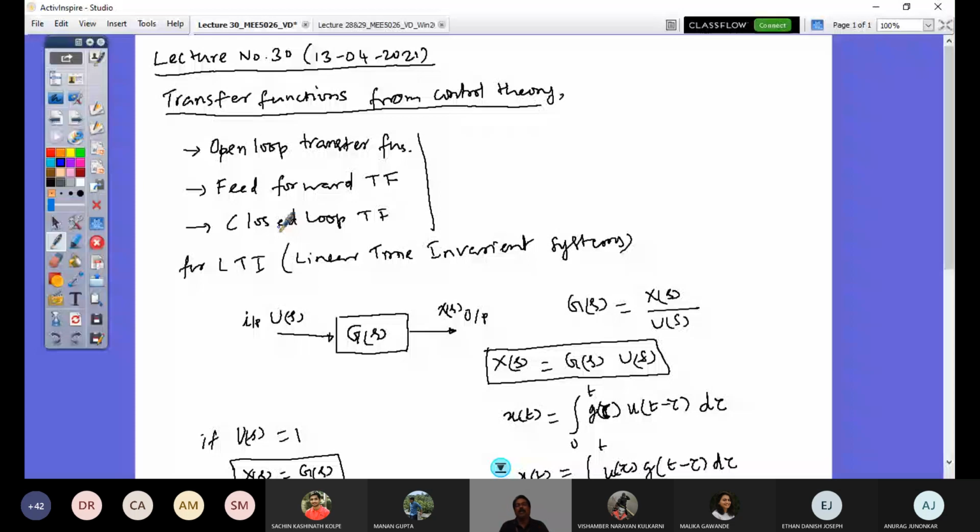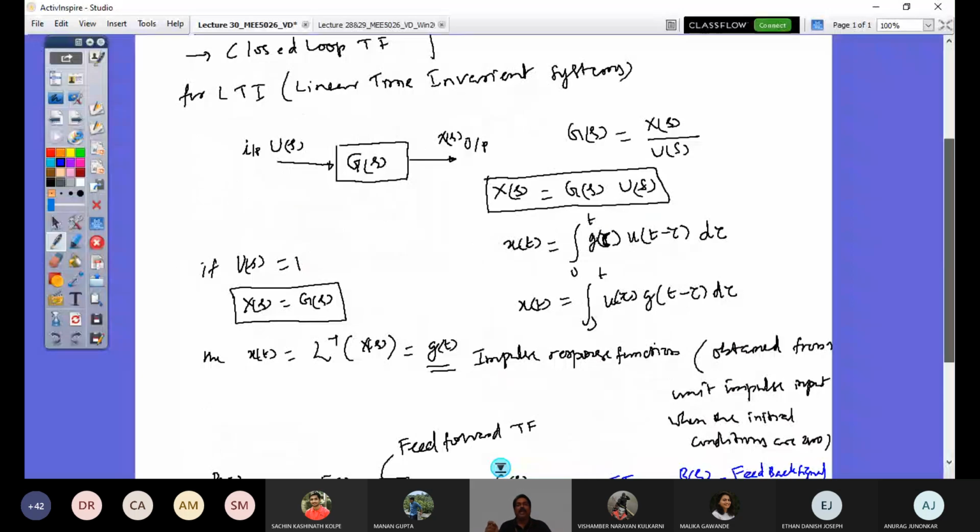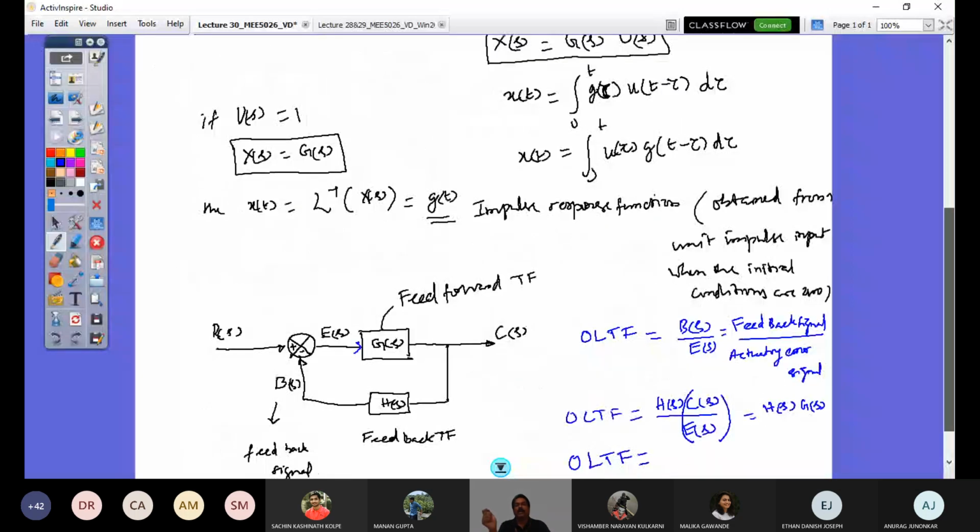Instead, I give a pulse steer input, and with that pulse steer input, I would get my transfer function, right? That's what I was telling, analogous to having a hammer and a physical mechanical system in the laboratory, giving an excitation and getting the response, you get your transfer function. Same way, to get the transfer function of your vehicle for a handling study, what you have to do is give an impulse steer input, pulse steer input, so that what you get would be your transfer function that would define the output.